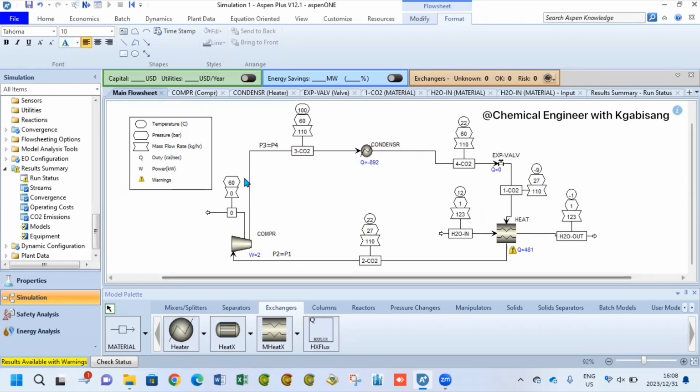So this process here is known as a refrigerant cycle, and it is used in most processes such as air conditioners, your refrigeration at home. It is a very, very complex process that's used in the industry. The reason why we have this refrigeration cycle here was simply to reduce the water from 12 degrees Celsius to minus 1 using a closed cycle. This carbon dioxide will continuously flow throughout the system from 3 to 4, 1, 2, just like that, as the water continuously cools off to minus 1 degree Celsius.